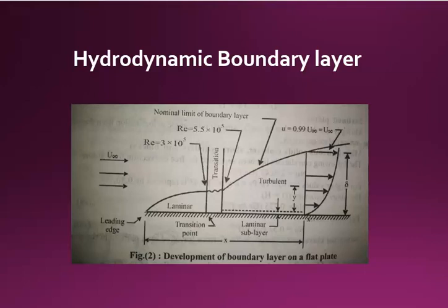However, the boundary layer is limited to the pipe radius because of the flow being within a confined passage. Boundary layers from the pipe wall meet at the center of the pipe and the entire flow acquires the characteristics of the boundary layer. Beyond this point the velocity profile does not change, and it is consequently said to be a fully developed flow. Further, the velocity gradient and the wall stress are greatest at the pipe entrance and drop to a steady value beyond the region of fully developed flow.